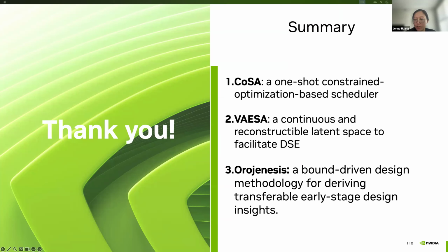Basically, as I mentioned before, if you think about the duplicated data access, it comes from the fact that outside of this buffered tensor, we're doing the loop iteration. So it's with respect to the data flow itself. If we're doing weight stationary data flow, what it means is that we are always reloading the input and the output regardless in the outer loop.